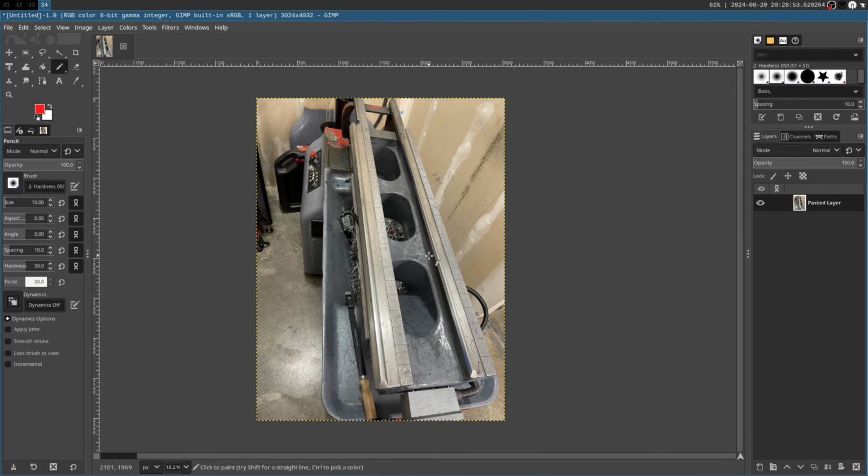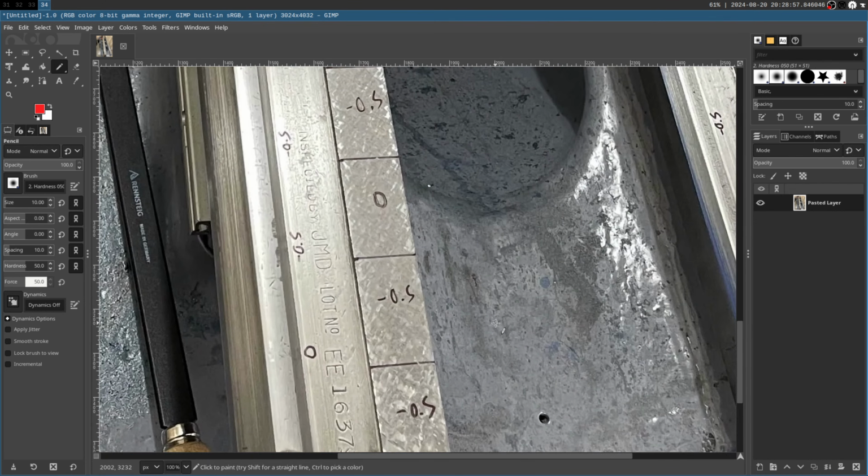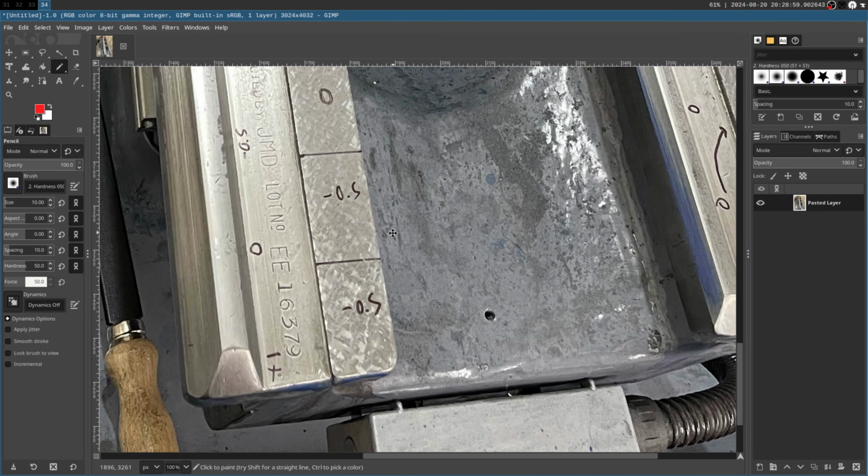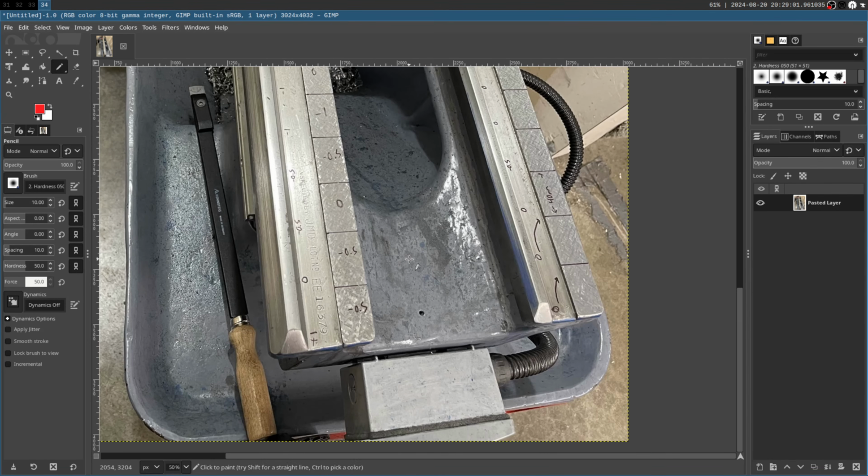Okay, so what I'm trying to do right now, and the only thing that I'm doing, is starting to make the reference surface for the lathe that I'm going to use for all other things. So this is going to be the true surface that I will make as precise as possible, and then everything else on the lathe will be derived with respect to this. And that is these flat surfaces here.